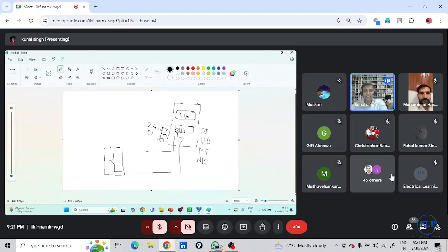So I am converting this voltage into a digital form, 0 or 1 binary, and this was connected to the gateway through some bus wires, communication wires. So here I have the option that when the binary input card input 1 is high, then I can put an address in front of it based on the protocol. Suppose I have a decimal addressing system. So the address may be 1000. So this input is now address number 1000 for me.